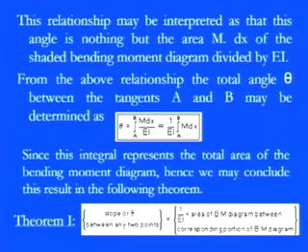And that is very much valid for a stepped bar. If you are talking about a non-uniform section, then for each different section, go with those portions, draw the bending moment diagram and multiply by 1 by EI for that particular section, and you have the slope, or theta, in between that section. So this is the basic principle of the area moment method.